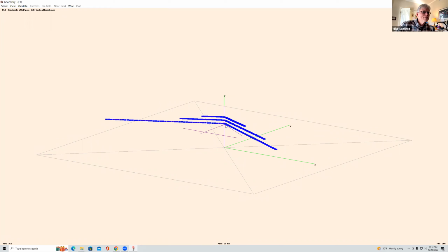If you can see, which is going to be difficult, I have an elevated vertical up about 30 feet, and it's then got about 24 feet after that. That elevated vertical has some big, long 17-foot custom radials. And then attached to the mast, or to the actual vertical radiator, is a 20-meter dipole, a 40-meter dipole, and an OCF. So I can switch the EX to any of these antennas and see how they interact. And of course, they all interact like crazy, but sometimes that's actually interesting.